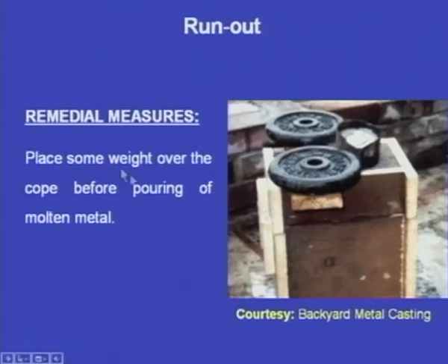Place some weight over the cope before pouring of the molten metal. By placing some weight, we can prevent this defect. The molten metal cannot lift the cope up because of these weights, then this runout defect will not arise.